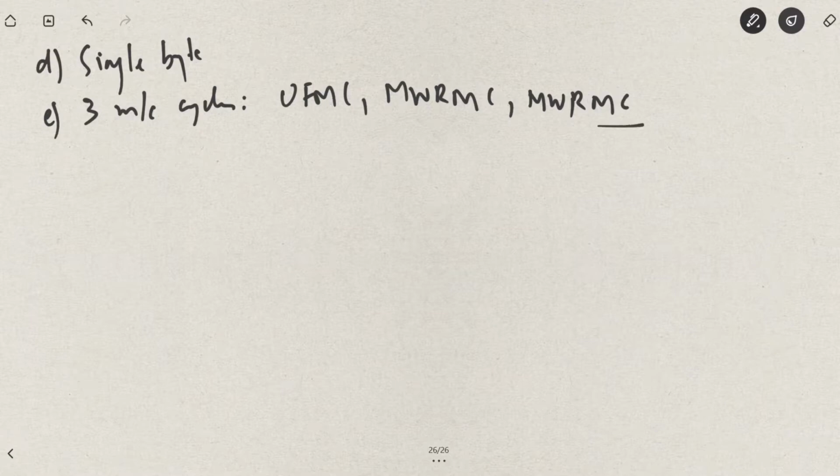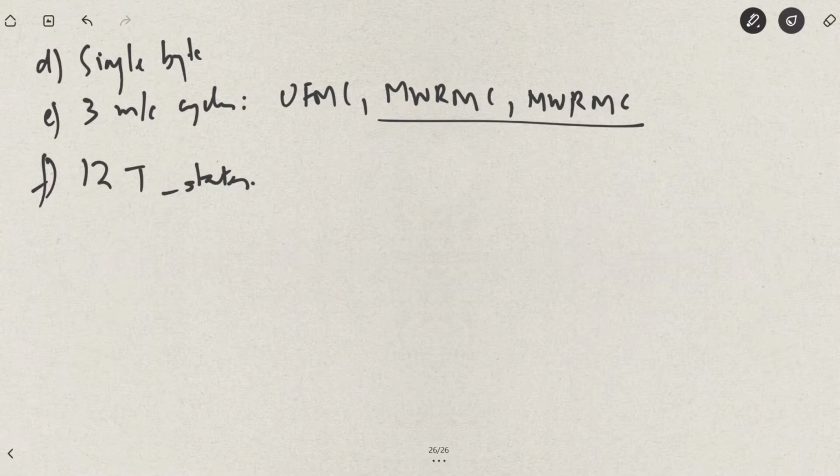For that we need 2 memory write machine cycles, so a total execution time of 12 T states, because the opcode fetch machine cycle in this case is of 6 T states, and therefore 3.84 microseconds.